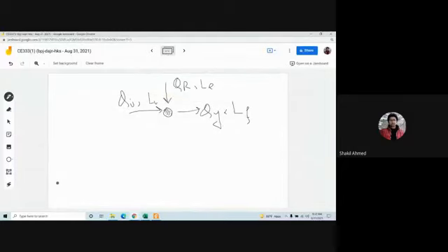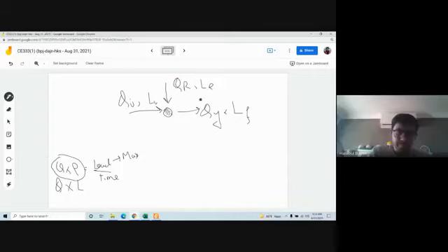Now tell me, Q into L. L is milligram per liter, so this is the concentration, rho, and Q is the discharge. So rho into Q is what? Load per unit time, mass per unit time. Mass per unit time equals rho into Q. Clear? Yes, sir.